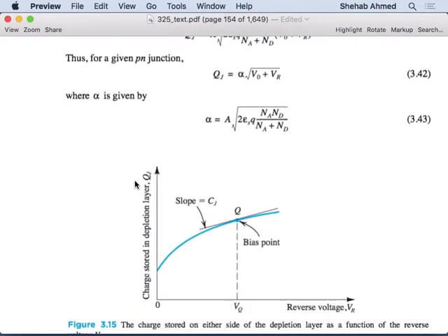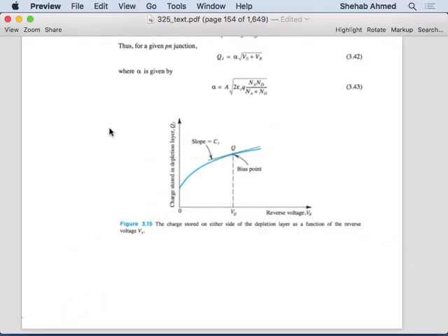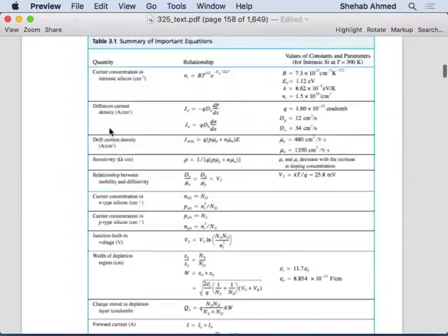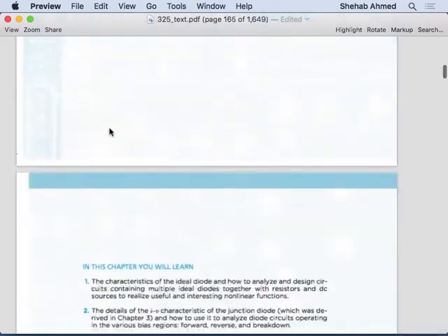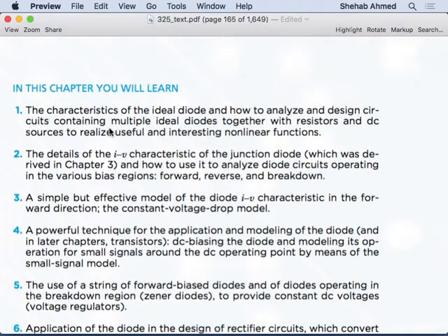This will become important when we talk about power devices, MOSFETs and BJTs later, because for you to start conducting, you'll have to charge or discharge a depletion layer. It will take time. So they will model that as a capacitance in the equivalent circuit. So that wraps up this discussion, and we will now talk in more detail about the diode from an application perspective.